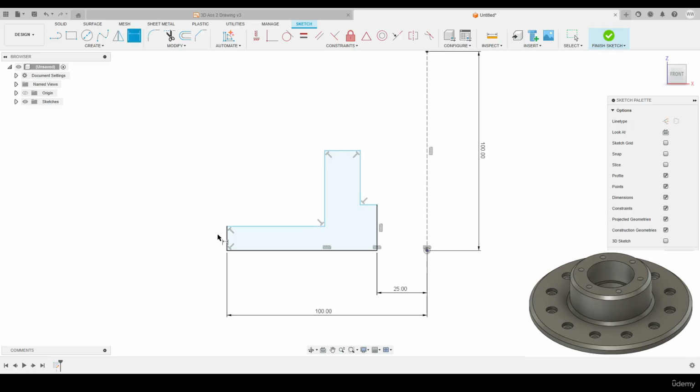We've got a wall height here of 10 mil. Put that in, 10 mil. We've got a distance from this line to the origin, and that is 100 divided by 2, so 50. And then we can do this line to the origin, which is 58 divided by 2, so 29.